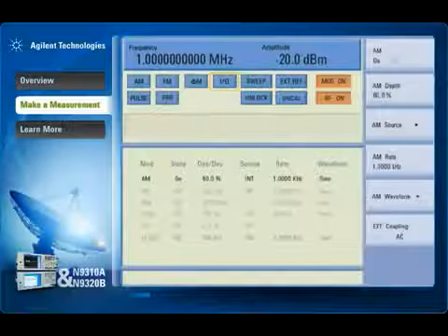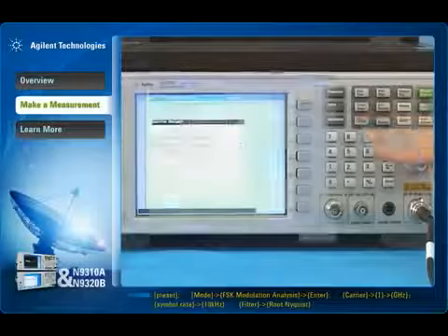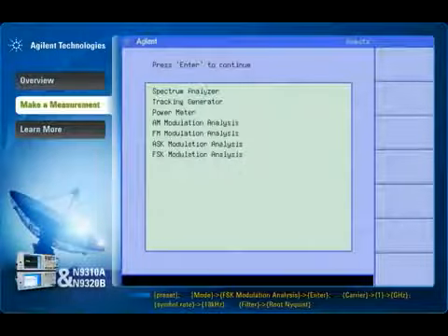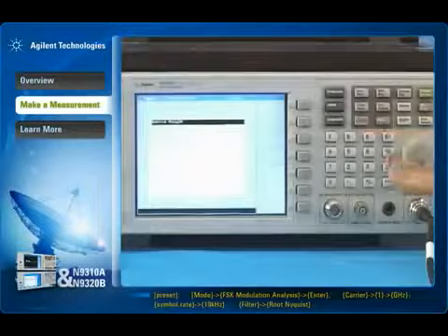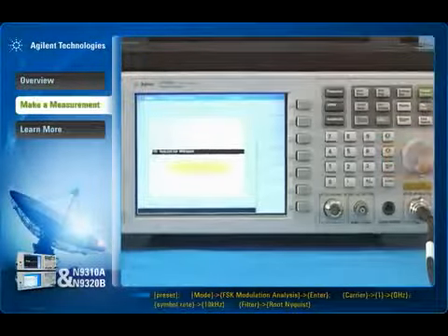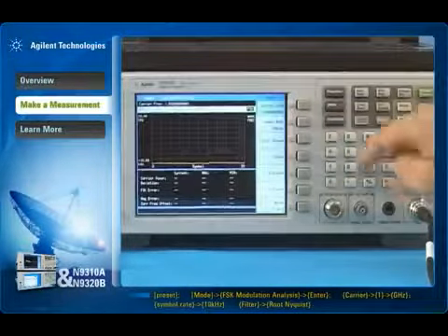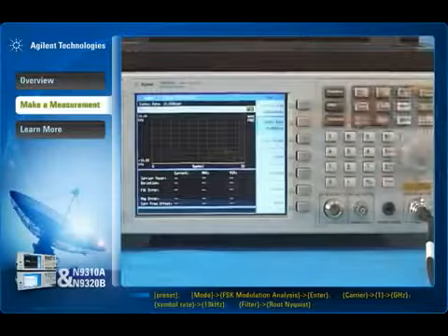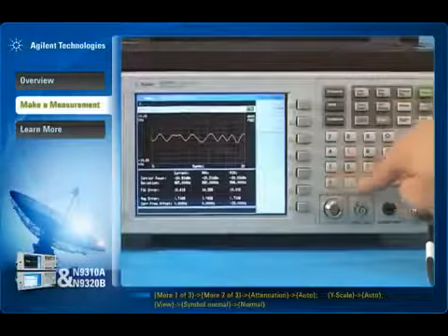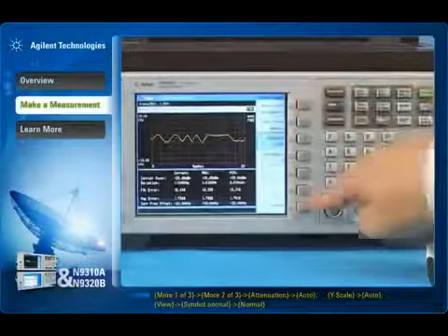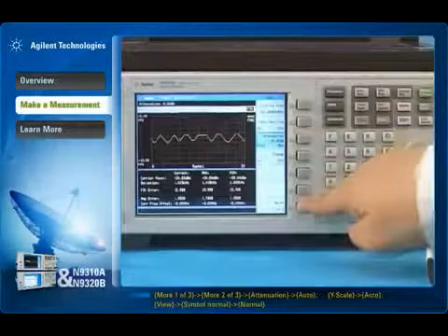Now we change the configuration to produce FSK signal. The N9320B option DMA supports the demodulation of ASK and FSK signals and also provides readouts for the baseband symbols, RF waveforms, ASK-FSK errors, and eye diagrams. The digital signal generation and demodulation can be widely used for manufacturing a variety of wireless products such as cordless phones, two-way radios, RFIDs, and wireless mice.